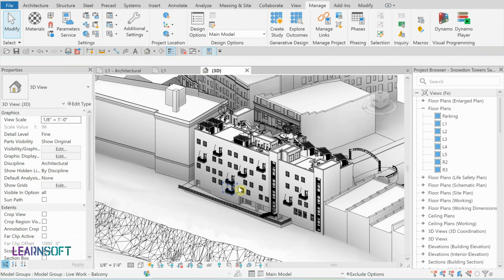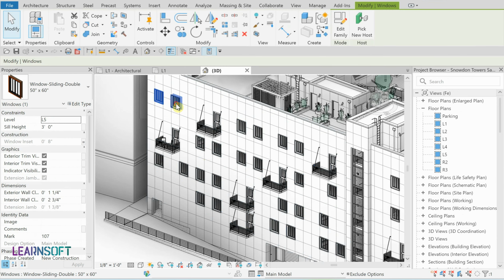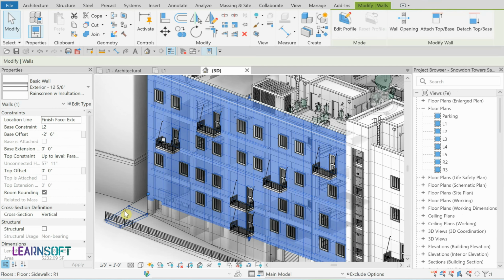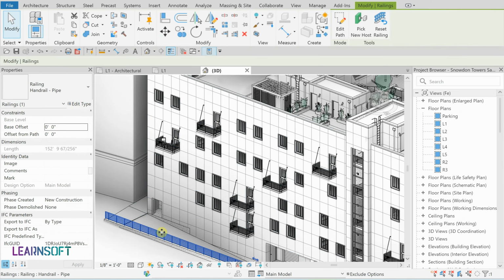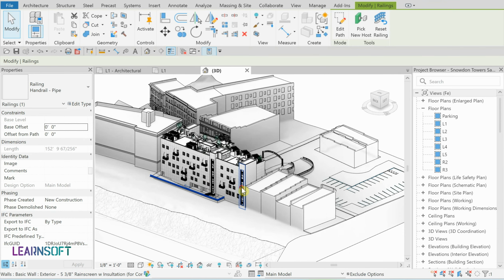In a project, the Modify tool is really essential. You need to select or deselect a set of elements most of the time. As you can see, by moving the mouse, the elements are highlighted. By clicking, the targeted element is selected. If you keep the Ctrl key, you can select a set of elements. Push Escape to deselect elements.